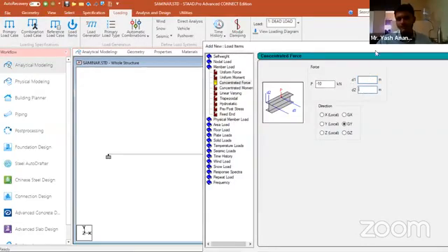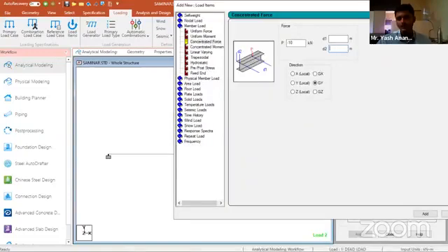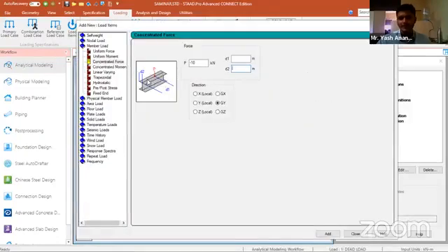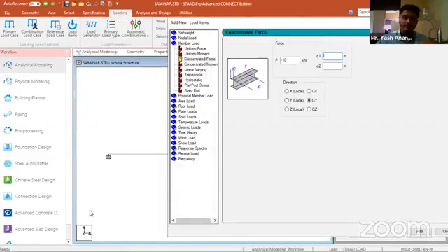But I want the load at the middle of the member, so I give this value as 0, 0. Okay, in the global y direction, right? I took minus 10 as it is a downward direction. Y is upward. If I took plus 10, it would be an upward load. But I wrote minus 10. Okay, so added.